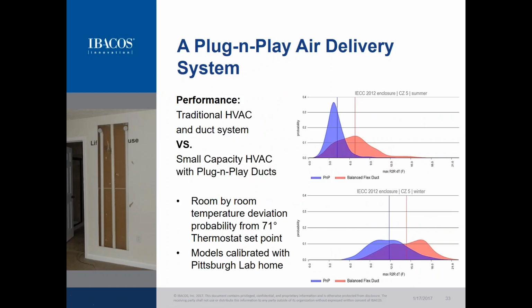So when we look at just the performance of the air delivery system, we actually have a lab home here in Pittsburgh that is an unoccupied home that we retrofitted, removed the traditional system, and installed a small diameter plastic duct system, and we monitored the performance of the system over a period of time. But we also did some modeling, using computer models to understand the performance, where we can model many homes across the country in different climate zones.